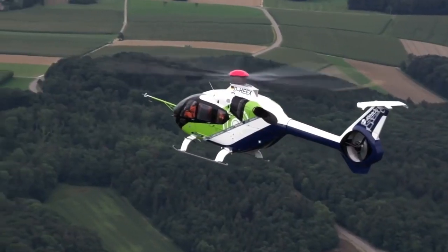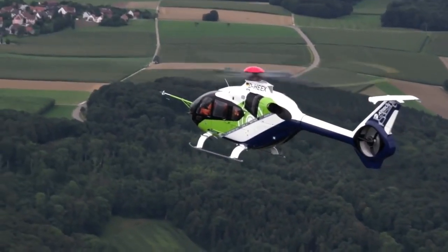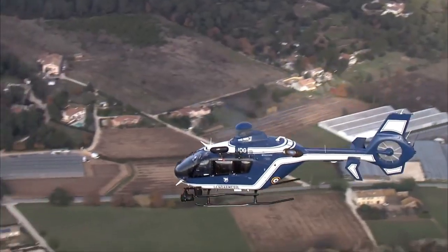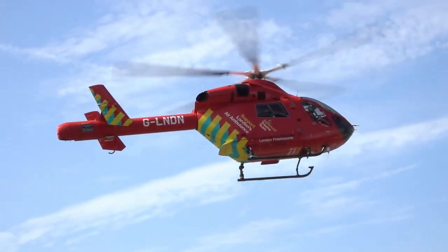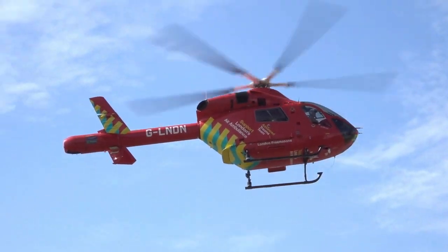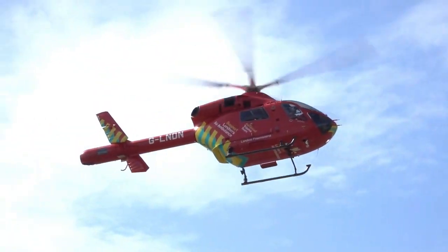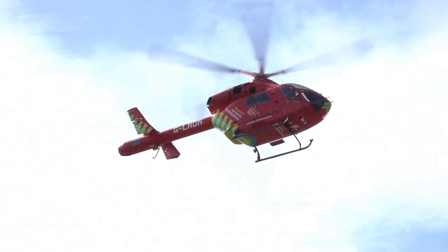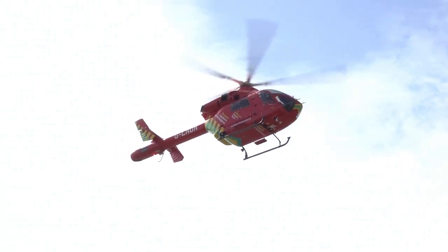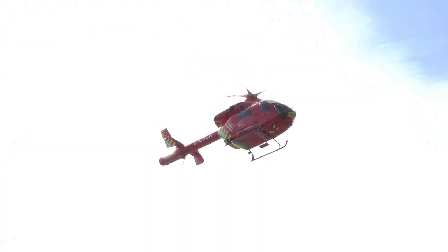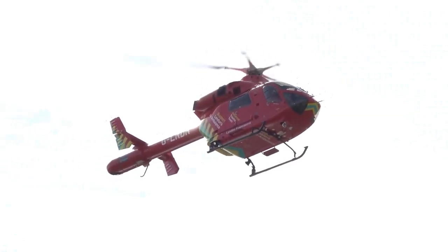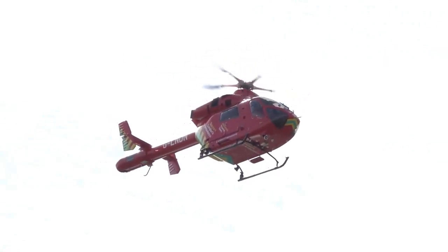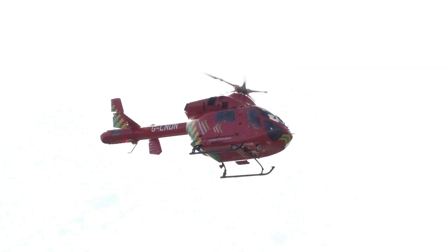Duct fans have between 8 and 18 blades arranged with irregular spacing so that the noise is distributed over different frequencies. NOTAR, an acronym for no-tail rotor, is a helicopter anti-torque system that eliminates the use of the tail rotor on a helicopter. Although the concept took some time to refine, the NOTAR system is simple in theory and provides anti-torque the same way a wing develops lift by using the Coanda effect.